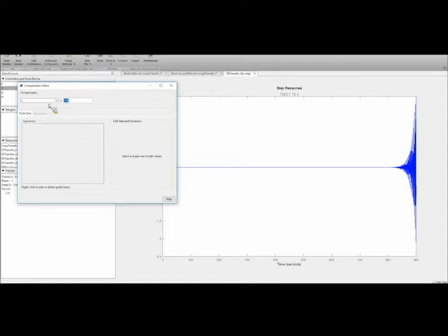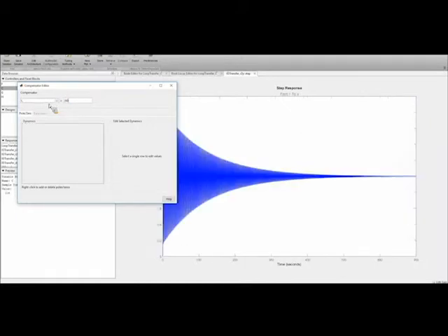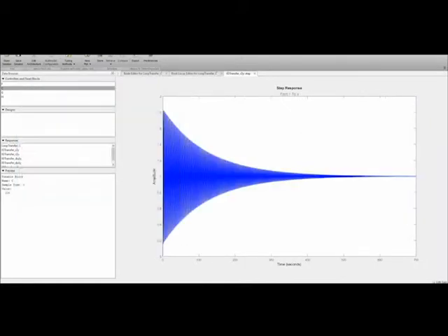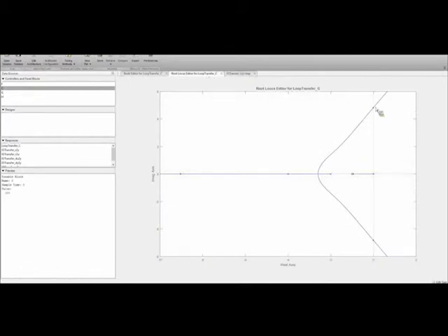say just at 200. All right, so it's stable, and this is defined by converging exponentials, but as mentioned, this would probably not be favorable performance, right? So once we establish this is stable, then we could modify things from here. And just to make sure everyone's on the same page, this is just barely to the left here. This is right on the cusp of being unstable.